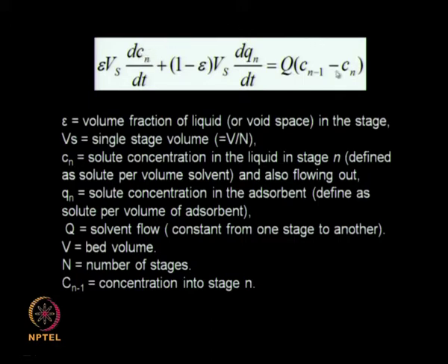One interesting point you need to note is that the concentration of the solute inside the stage n is the same as the concentration of the solute leaving the stage n, that is why here we have put Cn as well as here we have put Cn. So please note that. In an ideal stage process, when there is an equilibrium between two streams or phases, the concentration leaving is the same as the concentration inside the stage. So by doing that we end up with this type of differential difference equation. This is difference, this is differential equation.